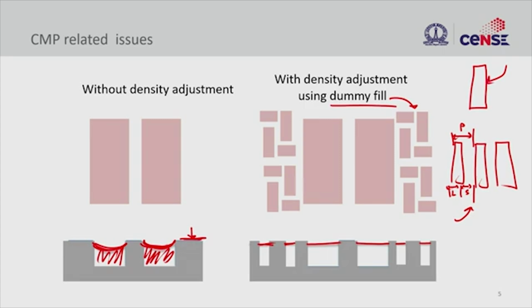The reason for that is the open space that you have. This open space is the reliability or process difficulty, where even the etch is going to be slightly hard, because you have faster etch in these portions, and if the isolated lines are not uniformly distributed, you will have etch depth variation.